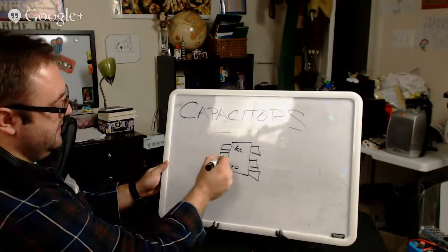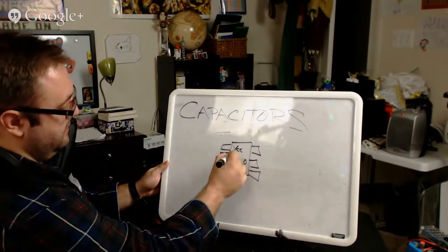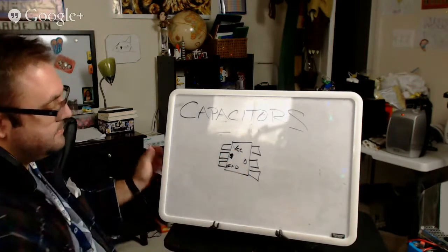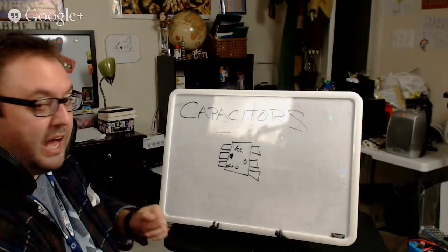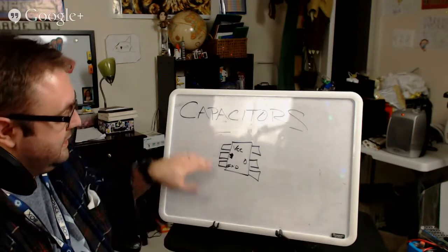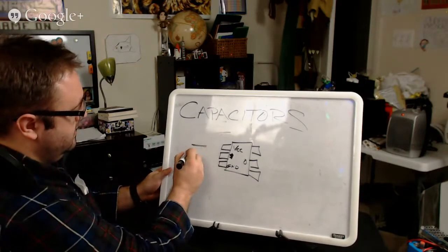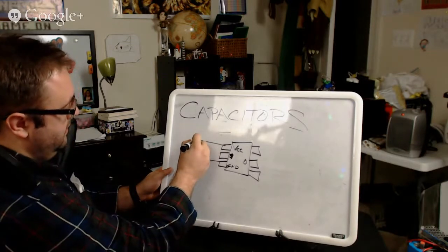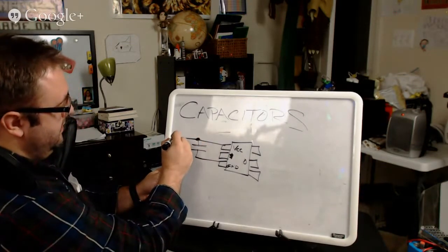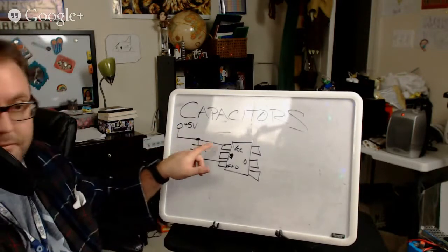And then you have your signal, all the different inputs, and then your outputs. The most common thing you'll see, especially around chips, is a capacitor across the ground and VCC. So somewhere down here, you'd have your plus 5 volts feeding into your VCC.